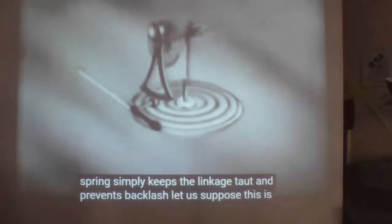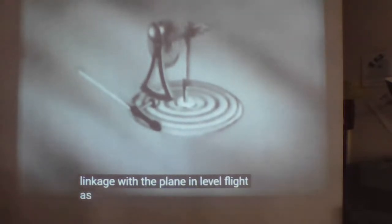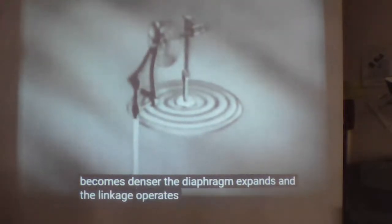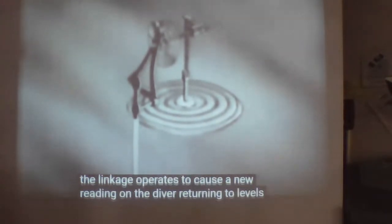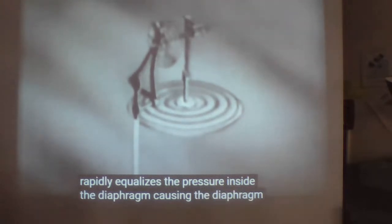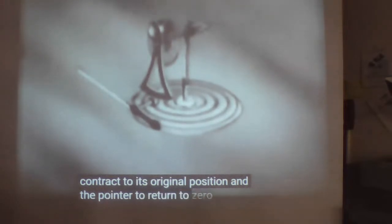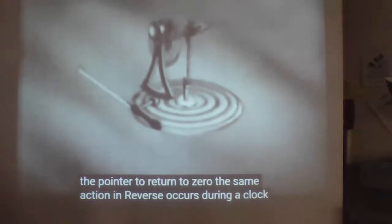Let us suppose this is the position of the diaphragm at landing with the plane in level flight. As the plane descends and the air becomes denser, the diaphragm expands and the linkage operates, giving a new reading on the dial. Returning to level flight, the pressure inside the case rapidly equalizes the pressure inside the diaphragm, causing the diaphragm to contract to its original position, and the pointer to return to zero. The same action, in reverse, occurs during the climb.